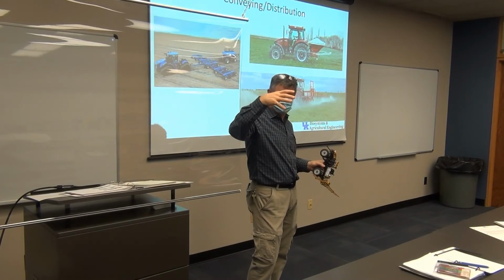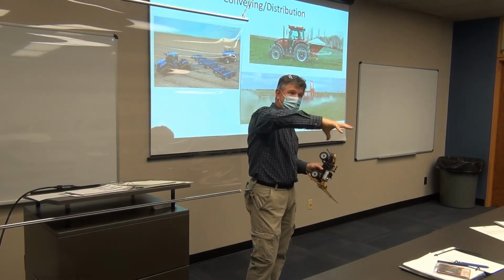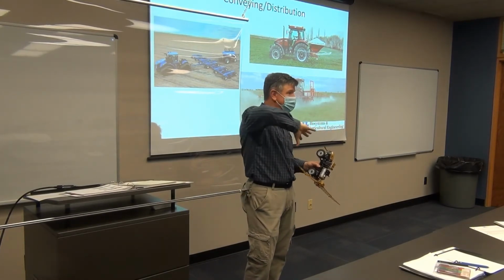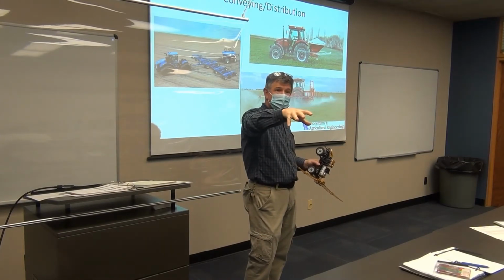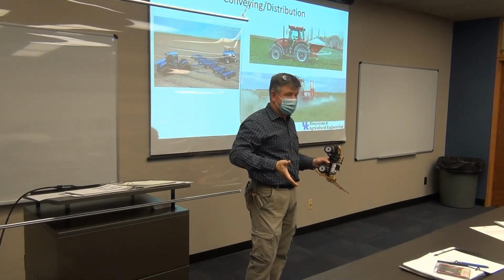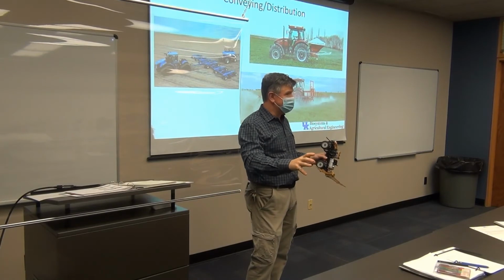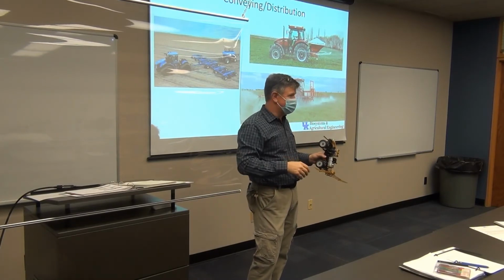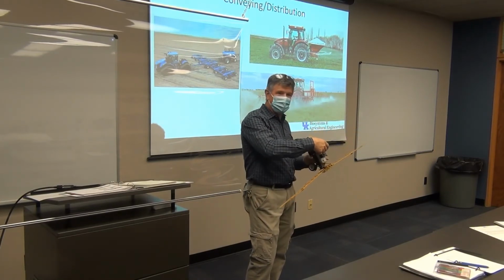Sometimes you get some aerial shots of fields and you can tell exactly where the path of the machine was. Every time the machine turned, I would have a burn on the inside of that turn because there would be too much chemical going in there. You can see those patterns in the crop. So being able to control at that level matters.